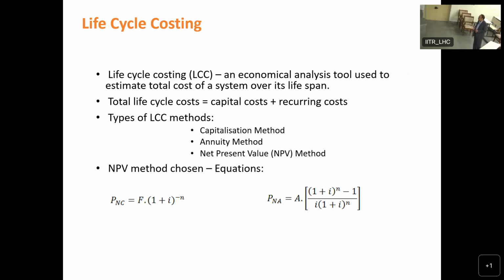So basically the idea is that when you are comparing this type of system, you are looking at the life cycle cost. That means conducting the analysis for 20, 30 years, looking at the capital cost, the operation, maintenance, replacement of the parts, and what manpower is required for operation and maintenance for that period of time, and then you bring that cost to the net present value.